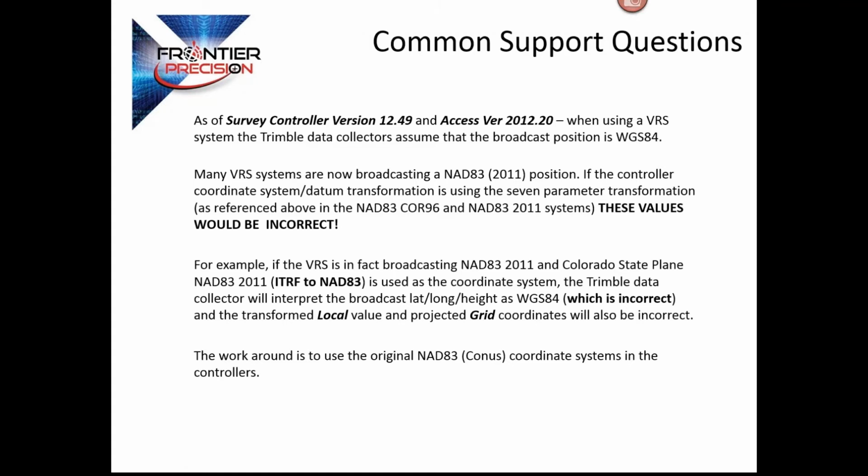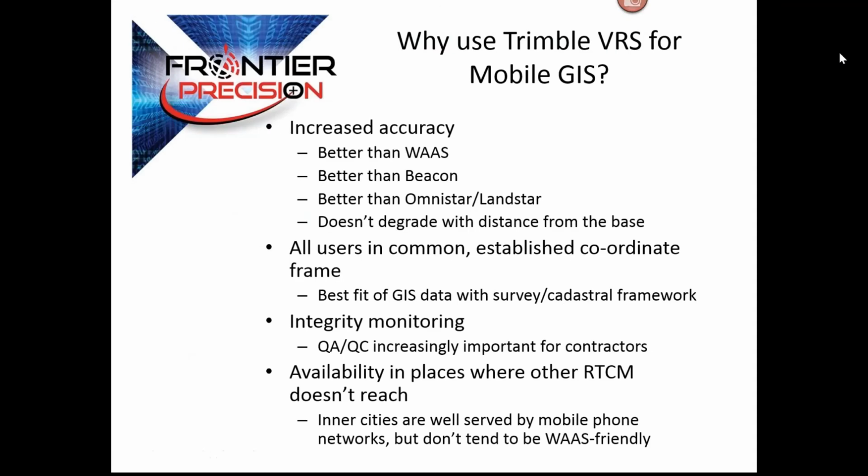For that reason, we always want to suggest to users to use the NAD 83 CONUS state plane coordinate systems in your controllers and in your software, and then you can transform from there to 2011 ITRF if you're required to do so. But when you're working in the field, we always suggest you use the NAD 83 CONUS selection within the data collectors. All right, I'll turn it back over to you, Mel.